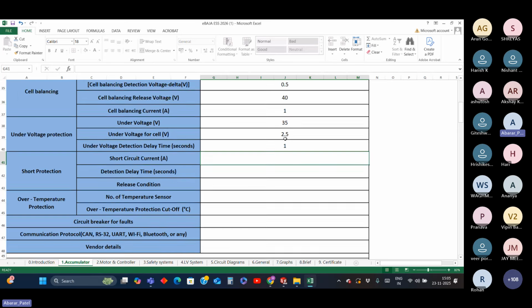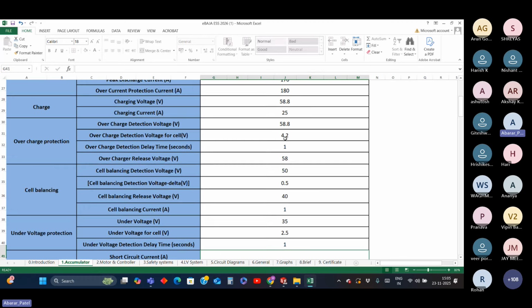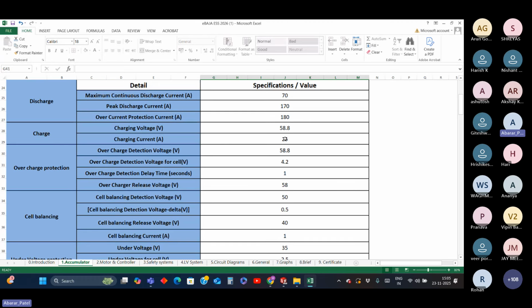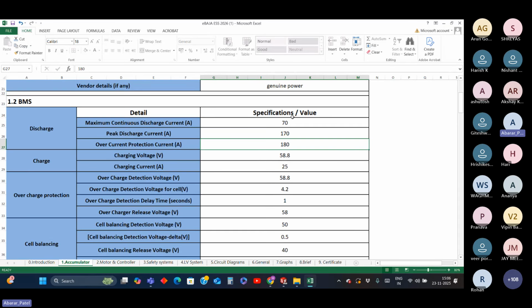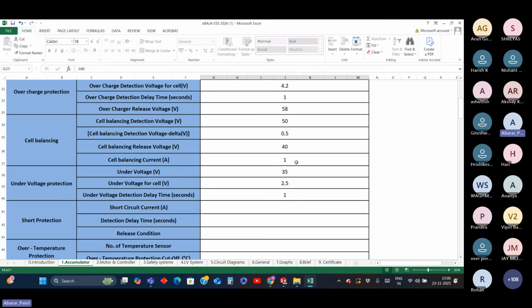Generally, short circuit currents are in terms of thousands of amps. Generally, higher current is fine. But considering our system to be a robust one and to ensure that it stays within your limits, we generally advise you to keep it around 180 to 200 amperes so that both of your limits will be hit. So let's say I will keep it around 200 amps.